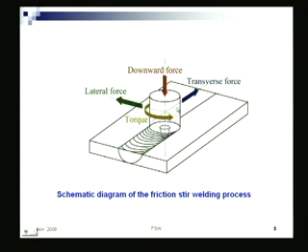Right. And there, if you apply further force, what will happen? Then this tool will try to plunge into the material, because here you see these lines, here the metal has got heated up because of the friction. So the metal here is soft enough. If you apply further force, this will try to plunge inside and will expel the material from these sides. It will sort of cut through along these edges. So how much downward force you are applying becomes one of the important parameters.